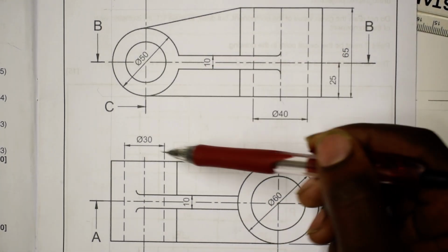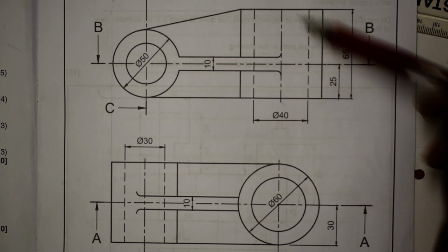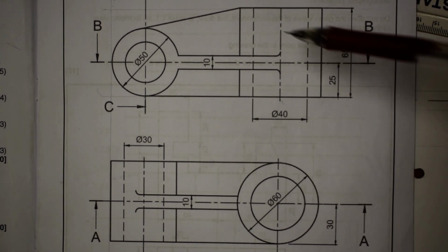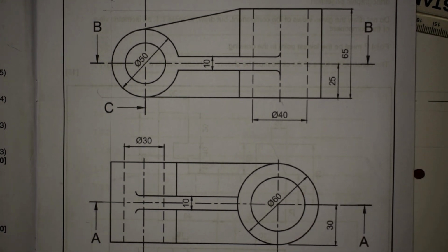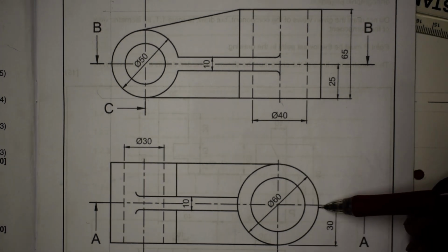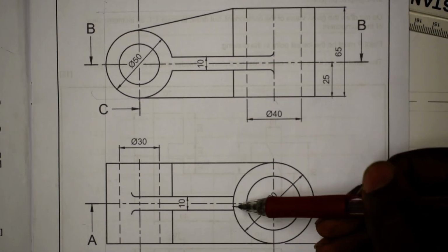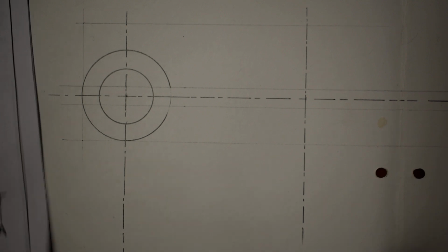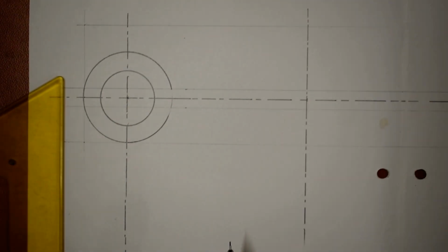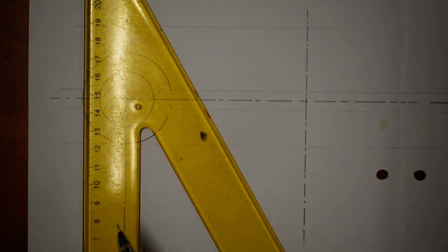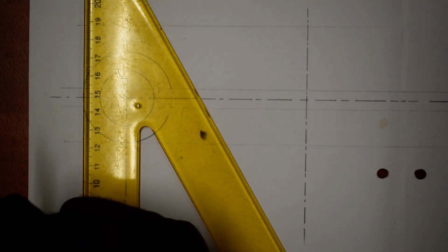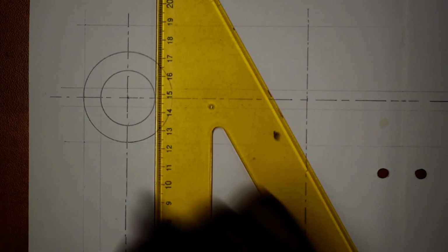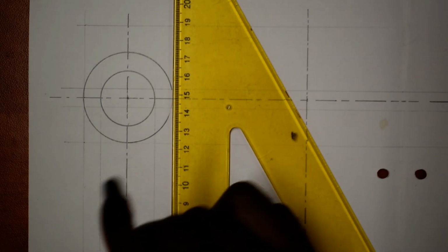So I've done with this one, so I'm going to construct them. If I approach to draw this, I might be a little bit inaccurate. You understand why? Because it's actually drawn right from circles, so it's better you draw circles first. After you draw, and then you take the circumference point, you understand? So like that you'll be accurate. So that is why I'll leave this part of my front view for now. You understand? So now I can take this point vertically down. There you go. So take this one. There you go. This one. There you go. Take this one. There you go.